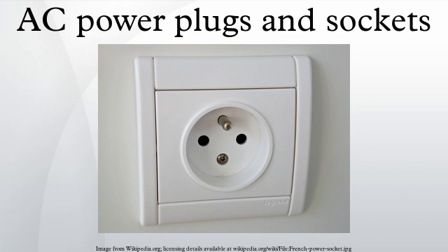US combination duplex socket. The parallel and tandem socket accepts normal parallel NEMA 1-15 plugs and also tandem NEMA 2-15 plugs. Both pairs of sockets are fed internally by the same supply.